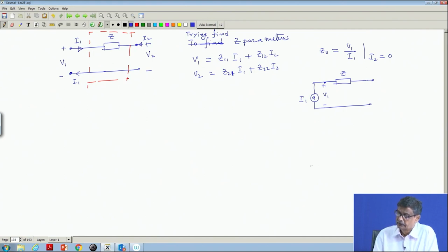Now, here is the trouble you can easily see: a current source, and here is an open circuit. So, what will be this voltage? A current source, as you know, always tries to force current. Impedance between these 2 points is infinity because of the open circuit. So this voltage will be infinity, and this voltage V 1 will also be infinite, because this voltage plus this voltage, this one is finite I Z no doubt, but this is infinite. And therefore, Z 11, if you want to find it, which you should not do, you know that a current source should not be kept open circuited, high voltage appears.